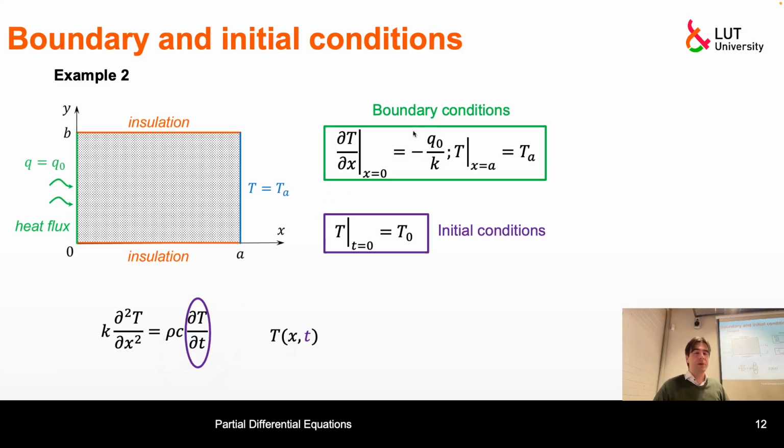This number of boundary conditions is another confusing topic. It looks obvious for this scalar quantity, the temperature propagation problem, because temperature is scalar, and we have a second derivative, so we have two boundary conditions, and with a first derivative we have one boundary condition. That's obvious in this case, but in a more general case, it's a little bit more complicated. We'll talk about that a little later when we talk about the finite element method.